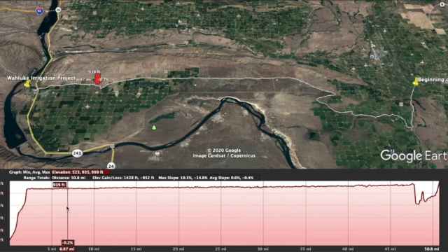And then finally, just before it drops over the edge down to the river, the elevation is 937 feet. In other words, the elevation has changed by only about 40 feet, maybe a little less than 40 feet over the more than 40 miles of canal that it has taken to get here.